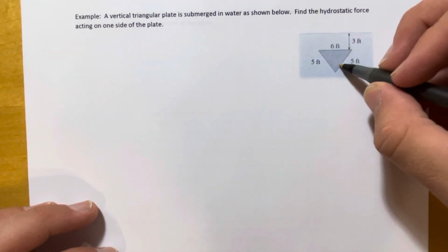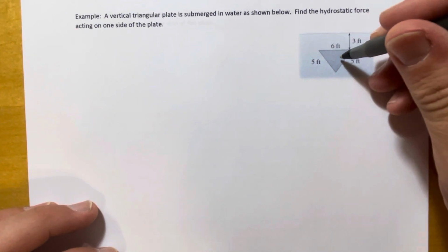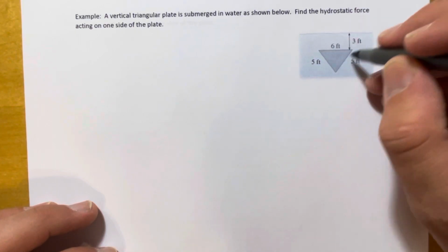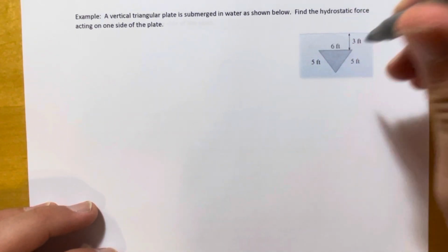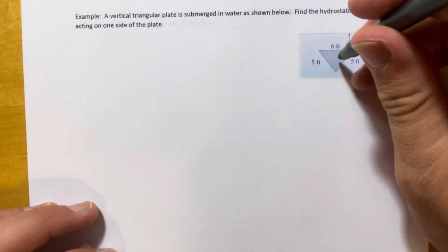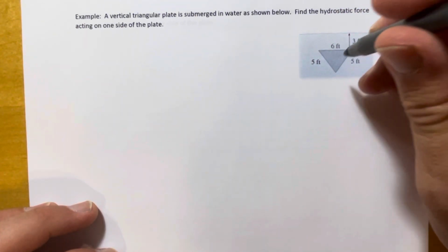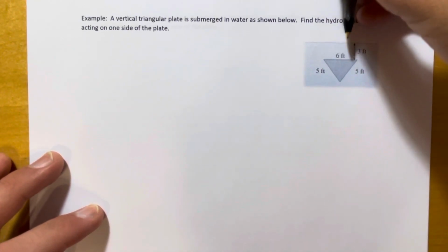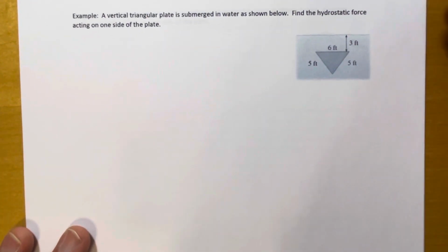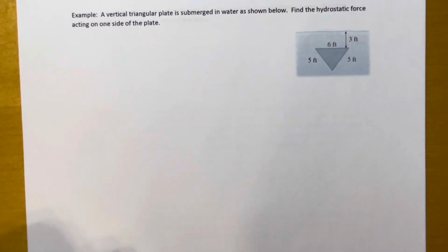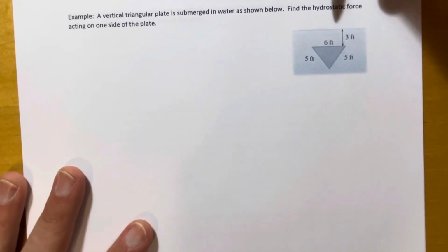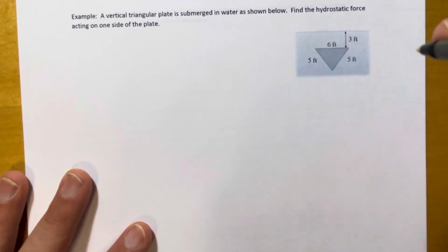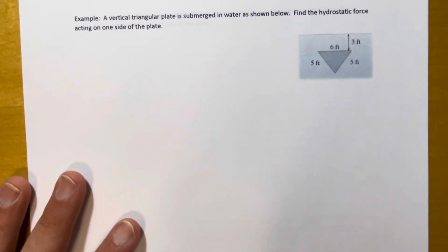However, at any given point on this plate, the force acting on that point is the same in all directions. So when we think of the force acting on one side of this plate, we're imagining that force going this direction, right? But at any given point, the force being applied in this direction, according to that principle we just talked about, is the same as the force acting downward on that point. So what that means is that we can apply all of the stuff that we did on the previous page, where we were specifically looking at downward force, and apply that to this force that's acting on one face of this triangle.